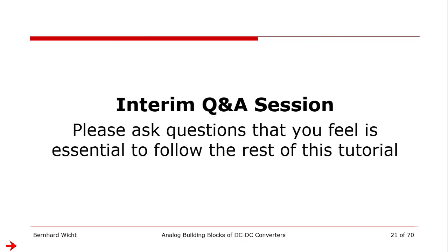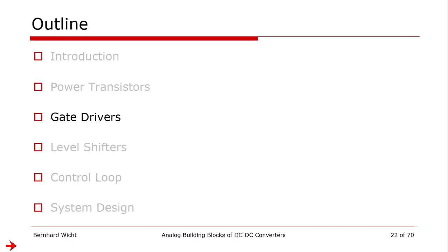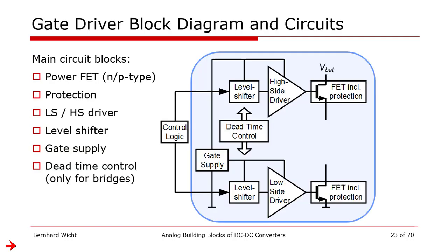So that brings us to the topic of gate drivers. A gate driver is a very simple circuit. It just needs to turn on and off the power device. So very simple, but if you look in detail, it's still a little bit more complex. On this slide we see there are, of course, the power transistors. Just as an example, I'm using here a high side transistor. This is the low side transistor. That includes also protection. Protection could be over temperature, protection against over voltage and over current.